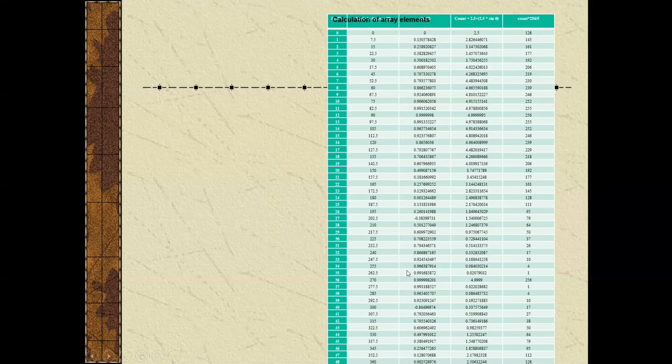There are 48 data values, and we cannot have a negative voltage at the output of the microcontroller. The sine zero level needs to be at the center, that is 2.5 volts, which acts as the x-axis. Hence we add 2.5 volts to every calculation, as seen in the fourth row of the table. Then we find the corresponding value for each voltage by multiplying it with the maximum count and dividing it by the maximum voltage, as given in the fifth column of the table.